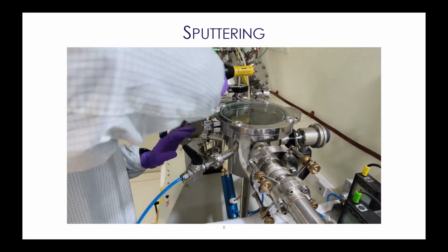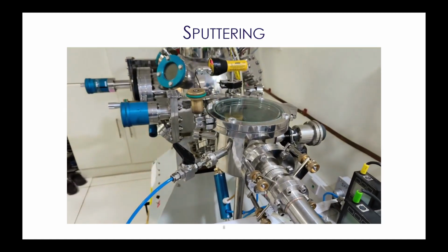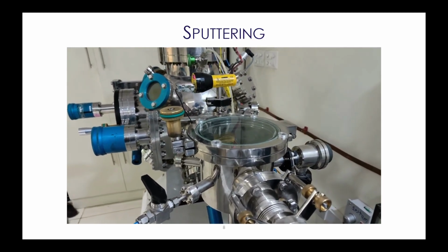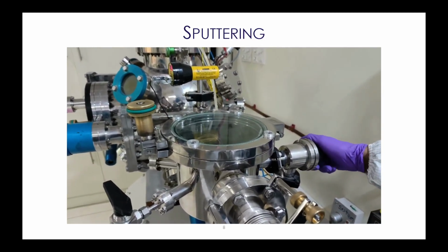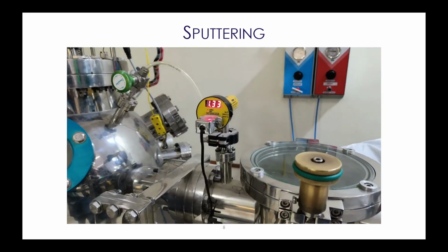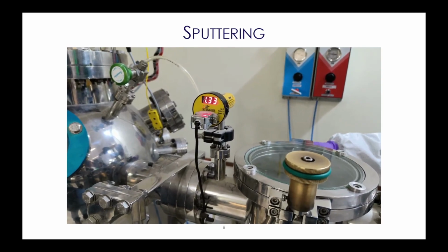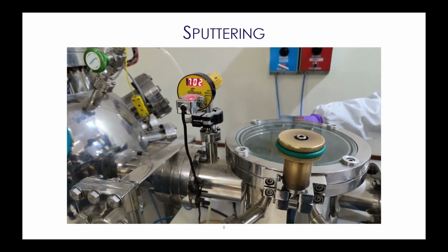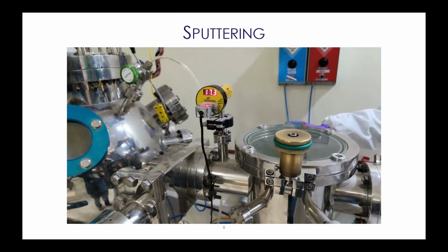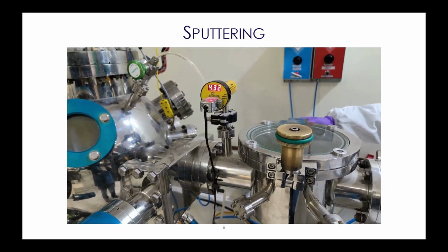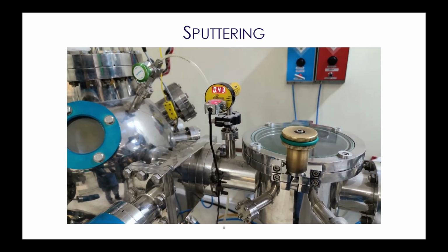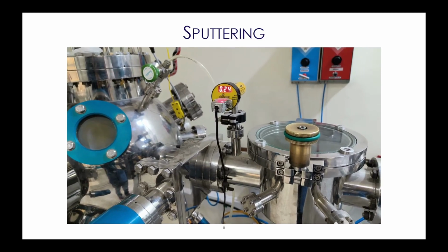So you have to load. You need to load a chamber. Now he starts the vacuum in the load lock chamber. It is called the LLC, load lock chamber. Then you have to open the load lock LLC gate valve, and then insert your sample in the sample holder, the rotator.